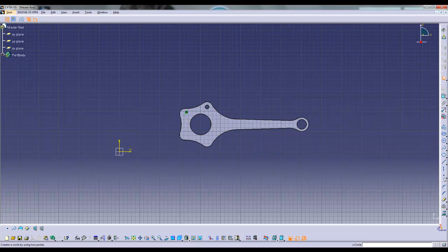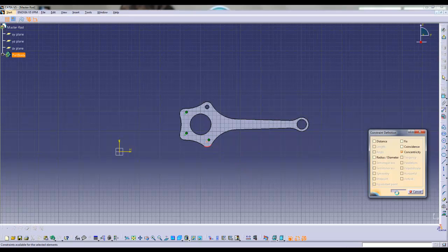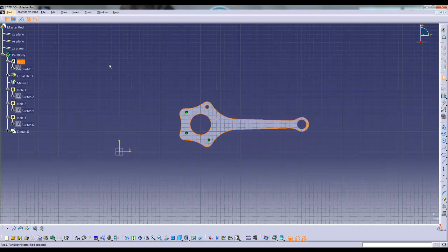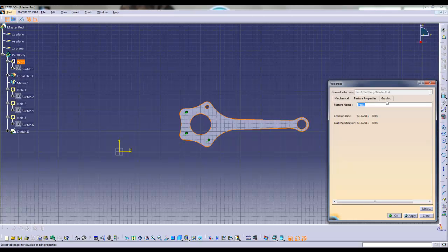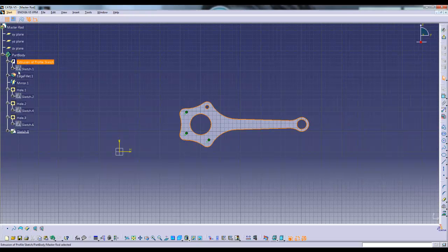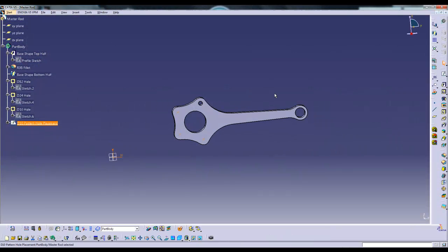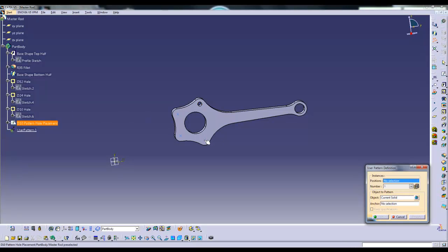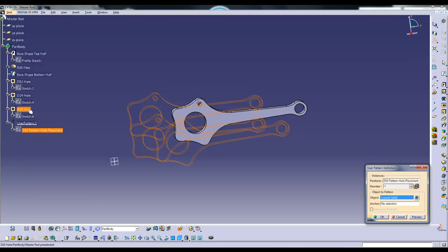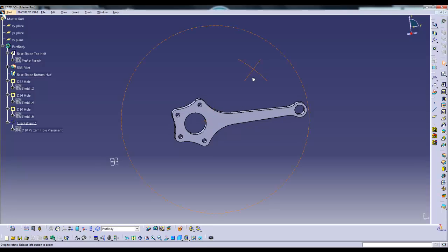That previous hole was 24 millimeters. The one before that was 52 millimeters in diameter. The hole you're seeing that was just created was 10 millimeters in diameter. The sketch that was just completed with the points placed concentric to the arcs as shown will represent the user pattern to replicate the hole with a diameter of 10 millimeters. Exit Sketcher. Select the hole that you would like to replicate using user pattern and selecting the sketch. You can now place the other 10 millimeter diameter holes.